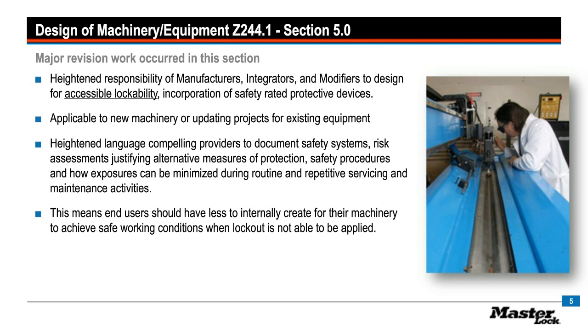Number one, to make more requirements for providing local isolation on the machinery that simply have to be hooked up to the power sources that are expected to come to the equipment. That will allow point of access rather than distant access, and will make it a much clearer process for applying lockout devices, tagout devices, or alternative methods.